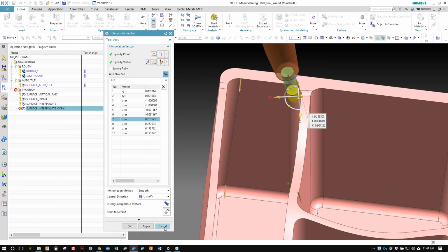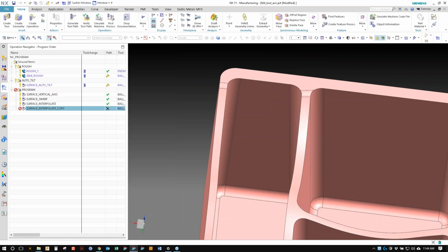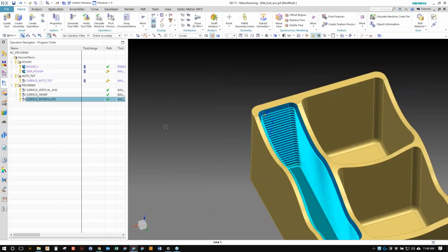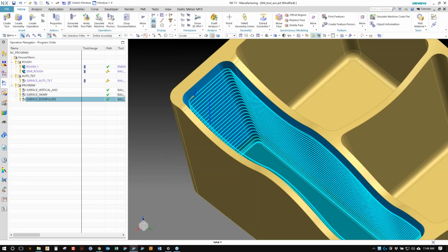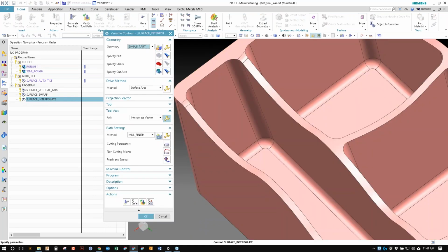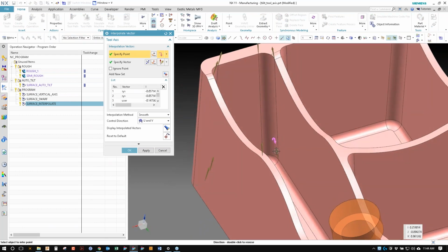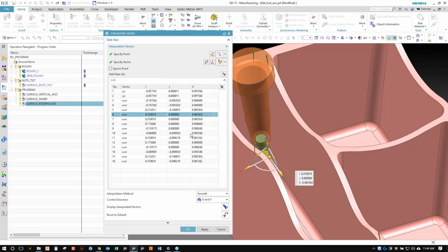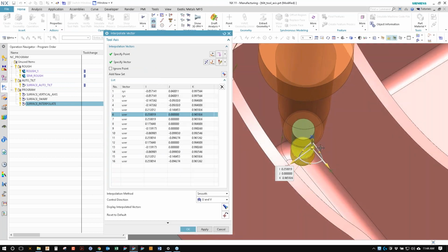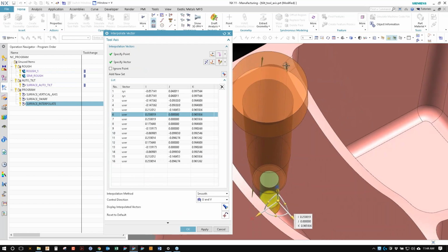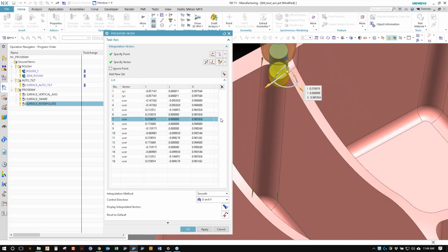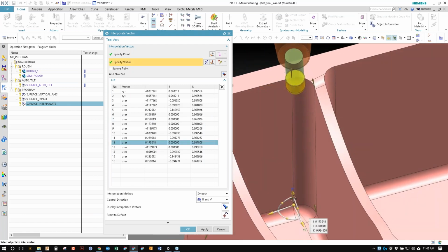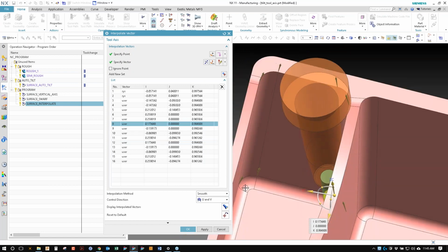So I'm going to hit cancel on this, and we'll delete that example. So that is this toolpath here. So you can see the toolpath looks good. Again, going into the interpolate, and to look at it another way, you can see the IJK. So here's this point down at the bottom of this radius, and then the point at the top. They have the same IJK value or same tilt. So going all the way around, the points that are vertical from each other have the same values.